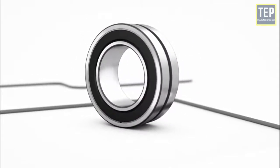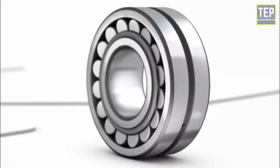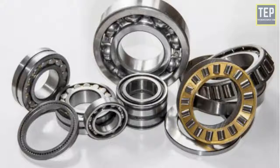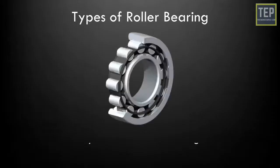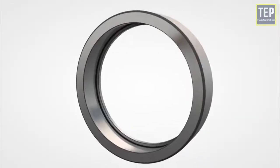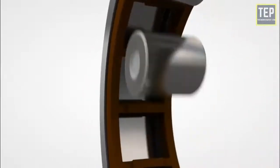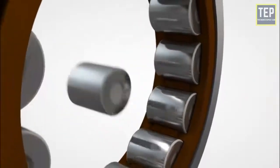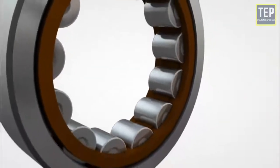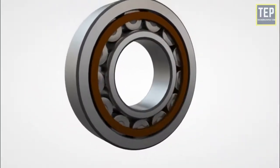Roller bearings contain cylindrical rolling elements instead of balls as load carriers between the races. In roller bearings, there are also various types, such as cylindrical roller bearings, which use line contact between the rolling elements and the raceways, which optimizes the distribution of stress factors at the point of contact. Cylindrical roller bearings have a very high radial load rating. Depending on the design, they may also be able to transmit limited amounts of axial loads.